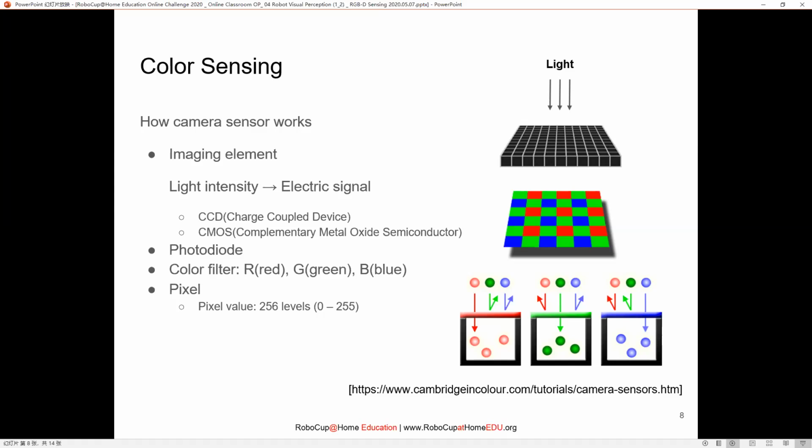But how about the color? Between the sensor and the light, we actually have a color filter. This color filter has a certain pattern in which it arranges the RGB filters. You can see one example over there. That is one arrangement, but we have various kinds of arrangements. With the RGB color filter, each filter gives you the value of the respective intensity of the color.